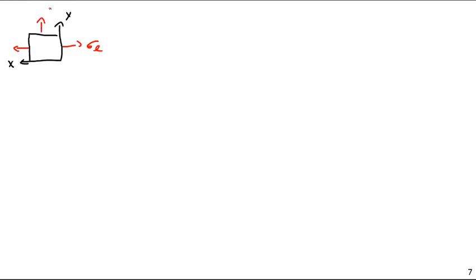This just comes right out of how my axes are lined up. So sigma longitudinal is going to be P R internal over 2t, and let me just write the formulas first. Sigma hoop equals P R internal over t, or simply 2 sigma L.